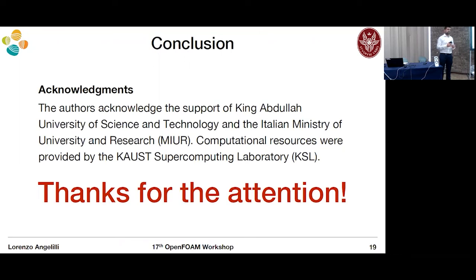So generally for FPV tables, the progress variable source term is very sensitive, but you show that it's actually not that sensitive, because even if your prediction has 40% error, the result is still quite the same. So I'm wondering what is the main reason for that, and also what is the cause of that 40% error? The question is basically that generally it was observed that for the FPV, the source term is sensitive to the progress variable and vice versa, and what is the source of the 40%, 50% error.